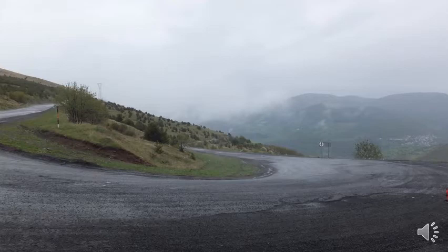Basically, cars are driving down that road and it's very steep, and they get to a corner and they're braking around the corner. And so in these places, that's where you're getting maximum shear force. And you can see what's happened there. The road, the wearing course, has worn away because of the shear force of the road.